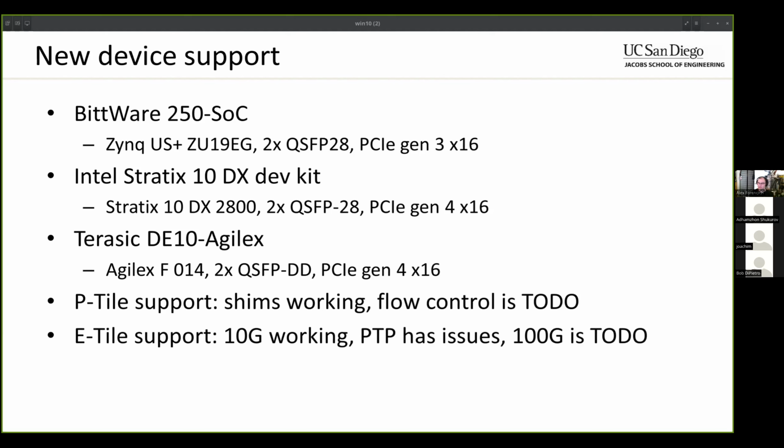The flow control I don't quite have sorted out yet. I took a crack at that over the past couple of days, and well, it didn't hang, but it didn't really improve the performance much. But I think I may have discovered what the problem is, and it's completely unrelated to flow control. I had some parameters in the config.tcl that didn't match the Verilog parameters that I was using during simulation. So in simulation, you get 100% throughput on the PCIe link, but in hardware, it seems like it was limiting performance quite a bit in a couple of aspects.